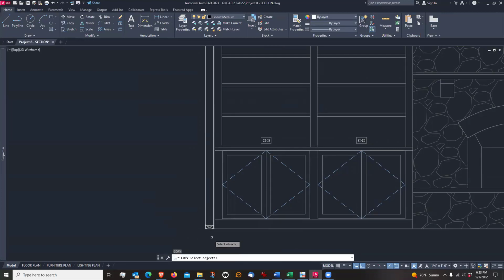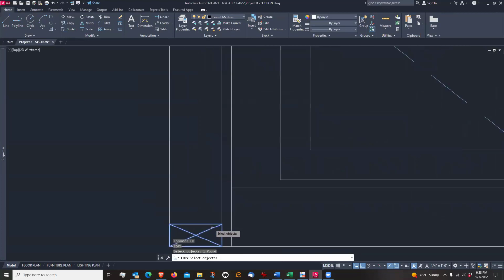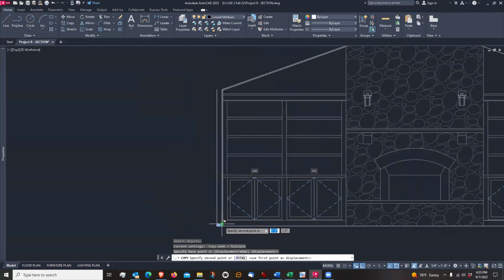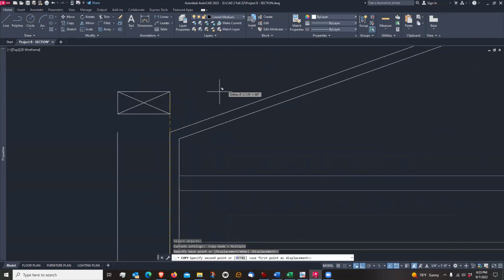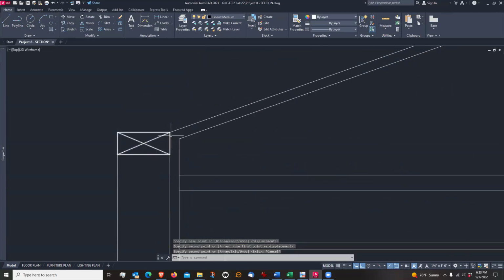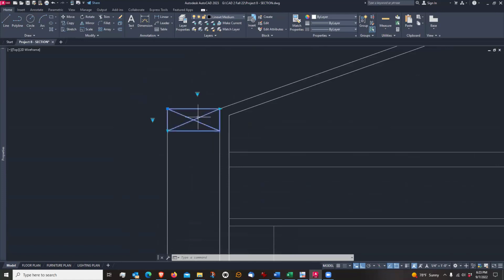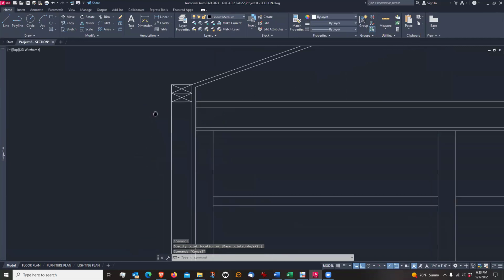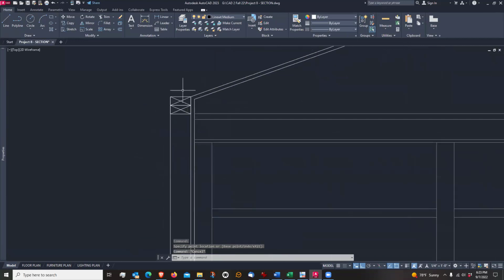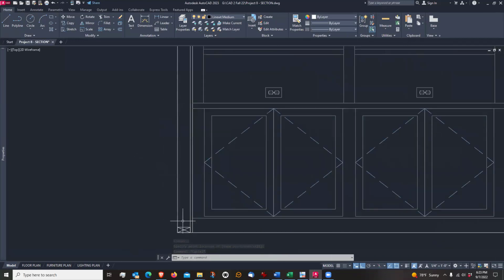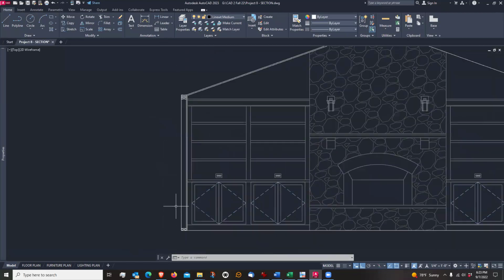And then so I'm gonna copy this, as I want another one up at the top, and I'm just going to put it right here, right where the back corner of the drywall is. And at the top of the wall, I do want 2 studs. So I'm going to pull that down. So I've got a double header. This is a header, and this is a sill plate or sill.